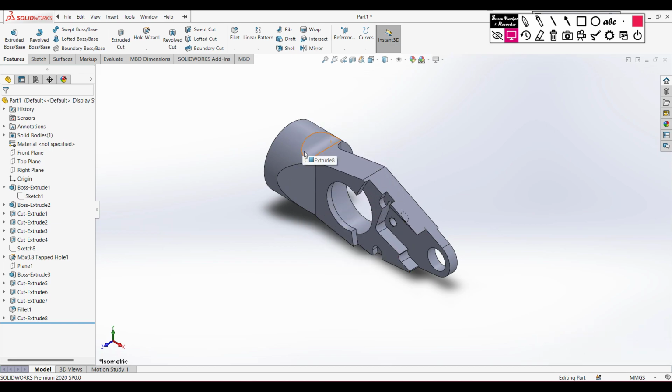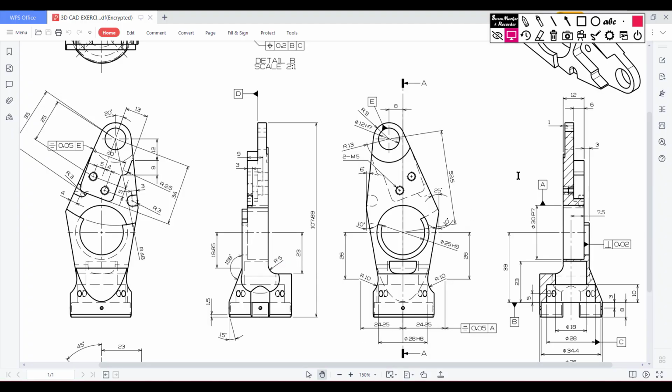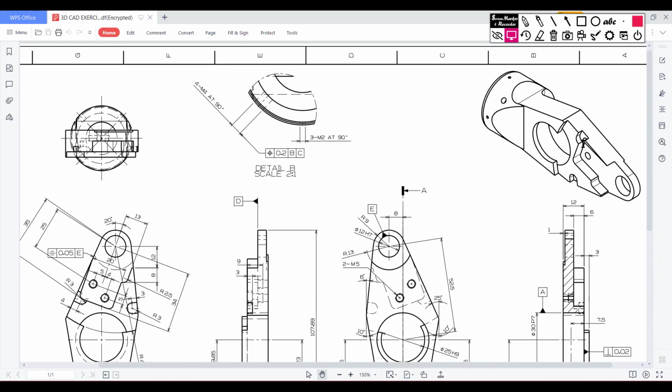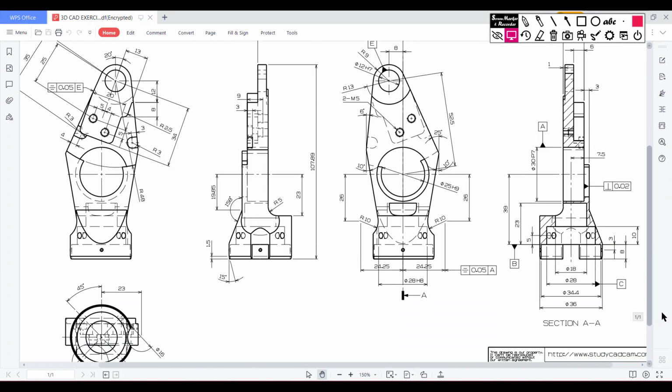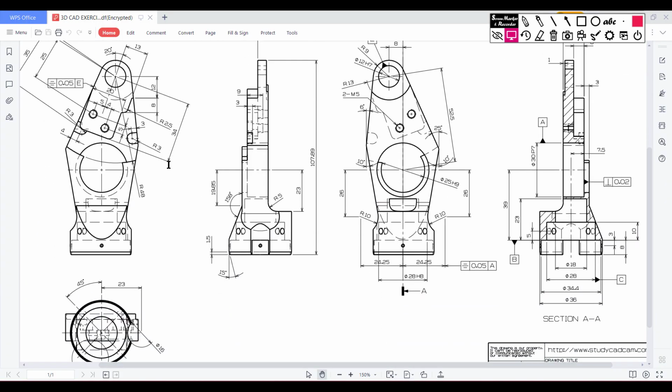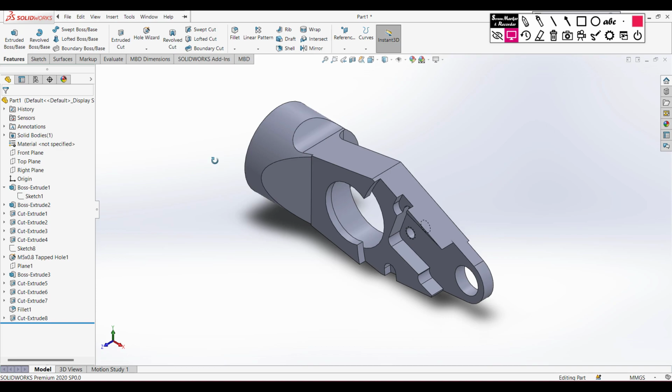Okay, now go to our sketch. So in our sketch we can see we have gotten this shape as we wanted. Okay, it is matching quite well. Now in our sketch we can see that we have some extrude cut here. First of all, we have an extrude cut circle of 34.4 unit diameter, and it has an extrude cut of 8 unit. So let me first do that. I'm selecting this back face.